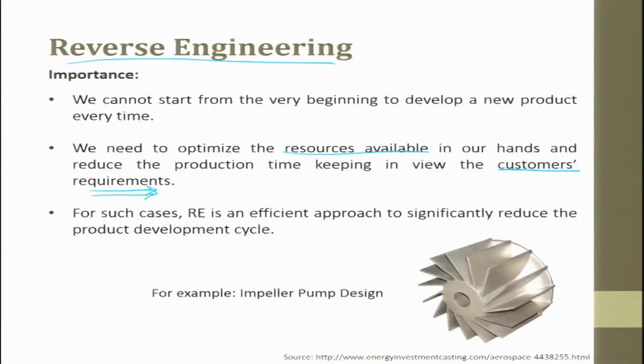So, for that we use reverse engineering exhaustively. For such cases, reverse engineering is an efficient approach to significantly reduce the product life cycle. You can see this is an impeller of a pump which is scanned, relooked at, and then you start trying to understand, do analysis and find out where the failure has happened, or what some other company has made. You scan it and try to get the data.